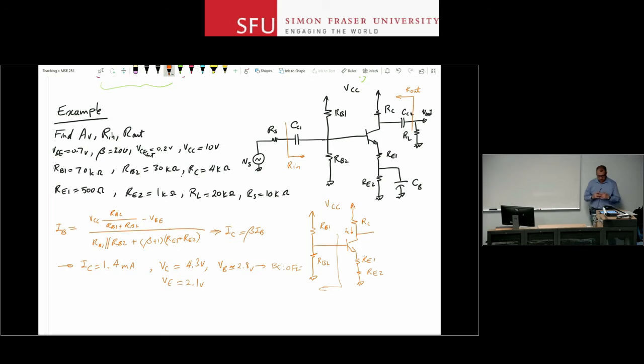What we are focusing on here is AC analysis. Now, I go back to that circuit, and I notice that at the core here, I have a signal that is produced by Vs and propagates through this circuit. I have a signal that is going into the base, so let's just call this Vi. It excites my transistor, and the transistor does something, and then something happens in the collector, which is where my output is taken from, right? So the input has gone to the base, the output has come out of the collector.